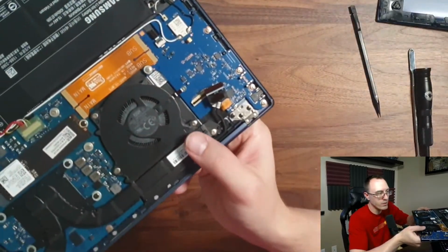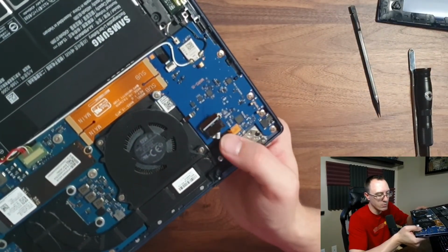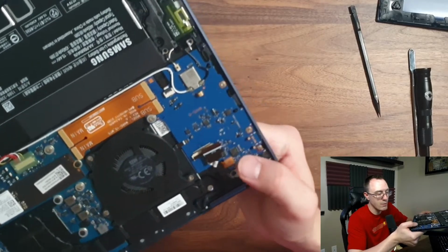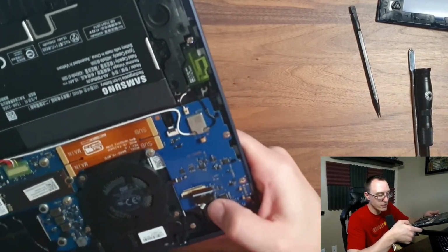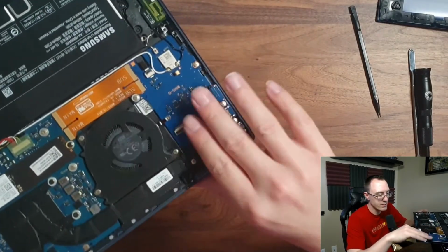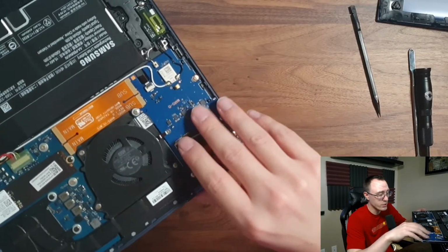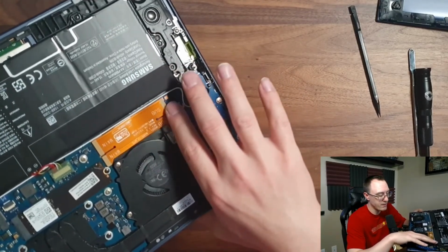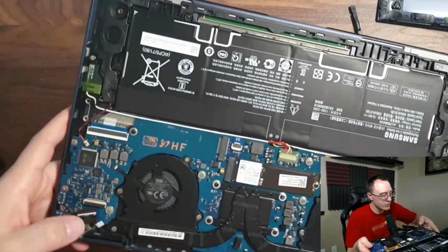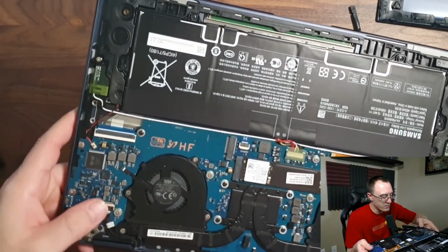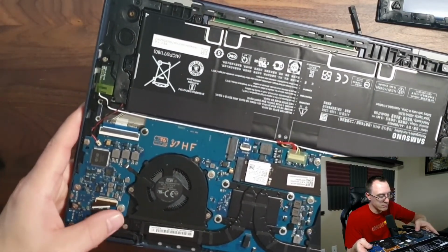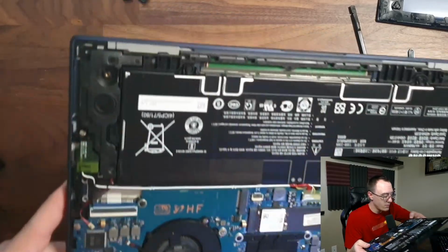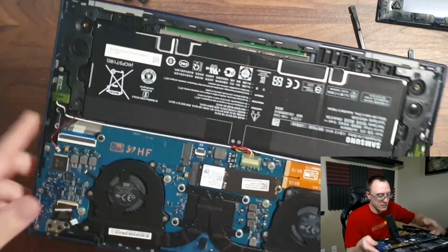And then this one is probably going to be the actual touch screen cable, because a lot of times they can be separate cables, but sometimes they are actually integrated. So the touch is on this side, which the touch works. So we know that this daughter board is okay. We know that this cable is okay. So that's not been affected. It's the screen that's not displaying anything out. So this cable is not really concerned to be a problem, but probably the entire LCD assembly itself.